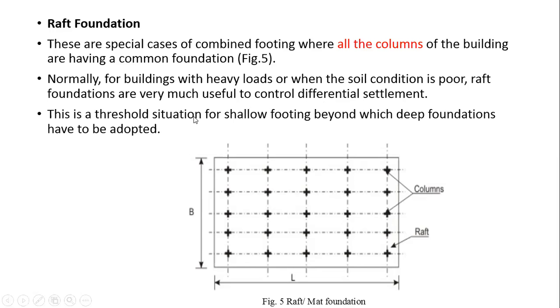Now this is a threshold situation for shallow footing, beyond which deep foundation has to be provided. So this is the last step where you can provide the shallow foundation. After this condition, you should always go for the deep foundation. Deep foundation means pile foundation.